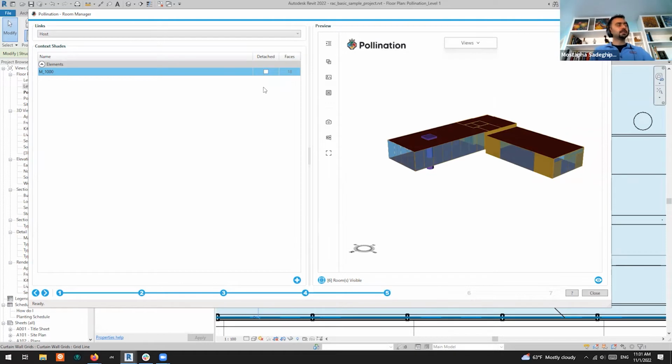you click. Right now, it's mainly for IES. Because in IES, there are two concepts of shade, of neighbor shades, and they call it, what's the other one, I forgot, local shade. So if you don't do detached, it means it's a local shade. If you do detached, it will be modeled as a neighbor building when you export it. That's the difference, and that's why you have it here. This will also be helpful later on for some advanced daylight simulations. But for now, we're good with this.